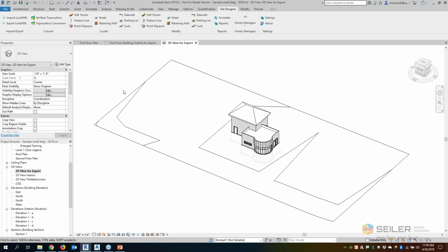I hope you can use this information in sharing your surface data and coordinating between Civil 3D and your Revit models using BIM 360 Docs and BIM 360 Design. You can use the shared reference points and export surfaces out without that as well, but it's a little more cumbersome. This is really a supreme method for using this shared data back and forth.